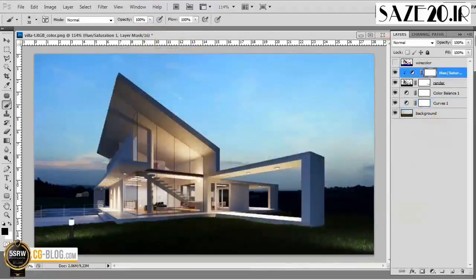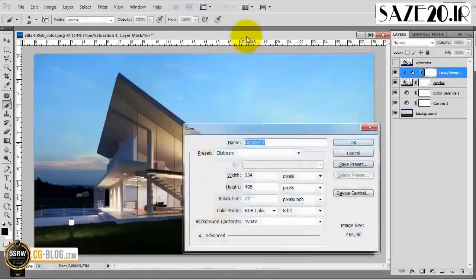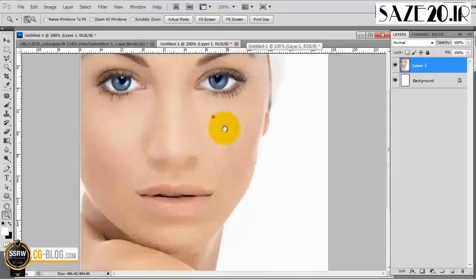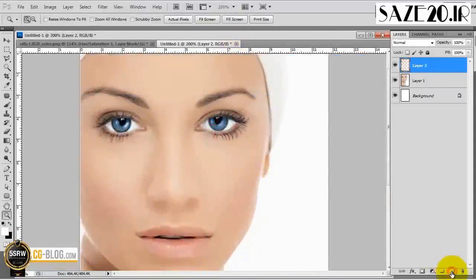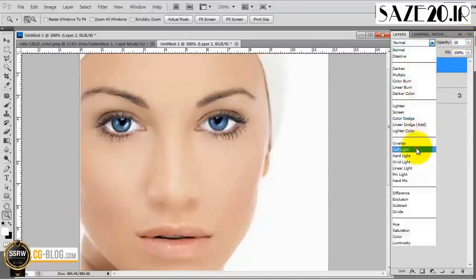We can improve by hand the contrast of our image as if we were painting. This light and shade technique is used by professional retouchers and is implemented with a soft light layer. This technique is used to model faces in real photos. Look at this example. Create a new layer, set it to 20-30%, in soft light blend mode.